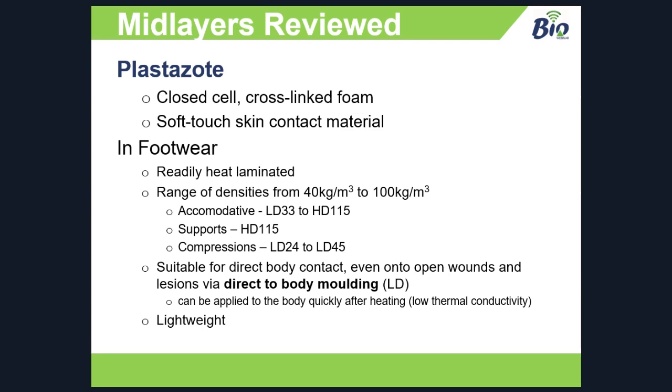Whereas a closed cell one, if they were all closed, you would squeeze it and it would resist. And so that brings back some of its resistance to the energy that we're putting into it. Okay, so Plastazote is interesting because it's a closed cell foam, so it'll get to a point and won't go any further, but it's cross-linked and the space between the bubbles is a bit more open.